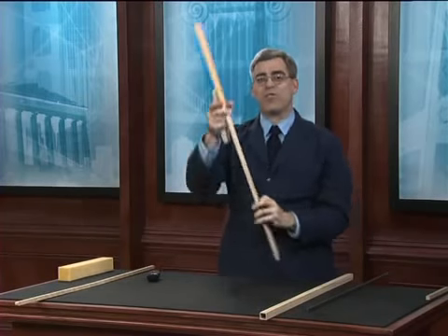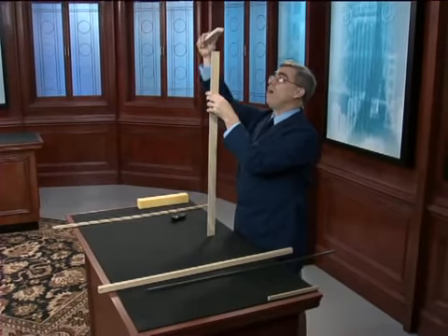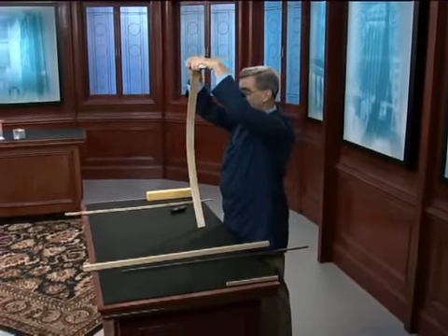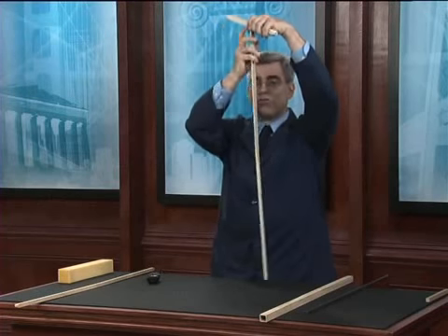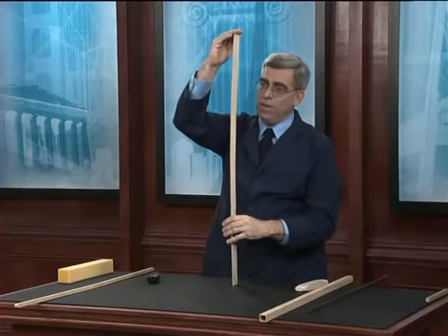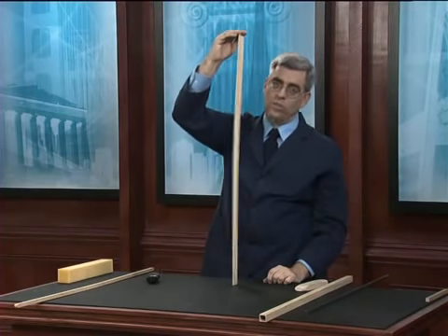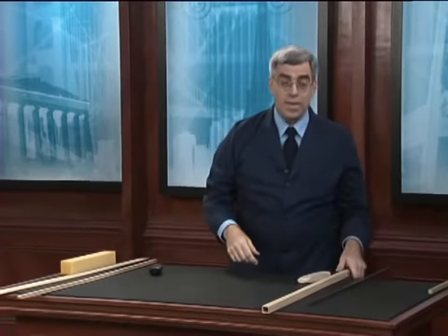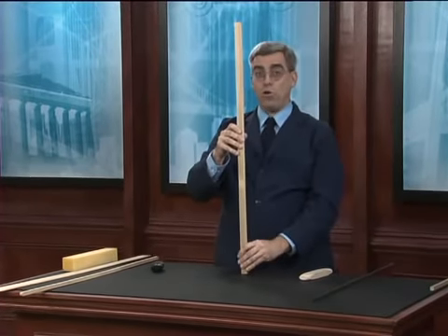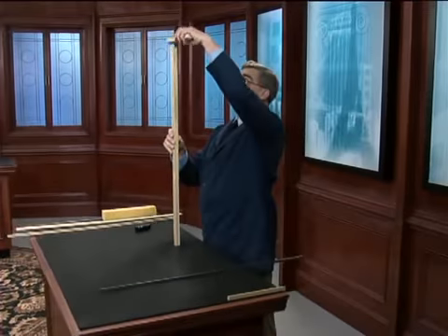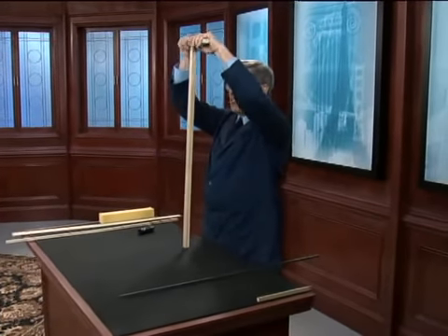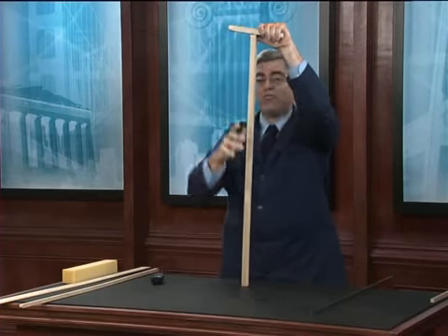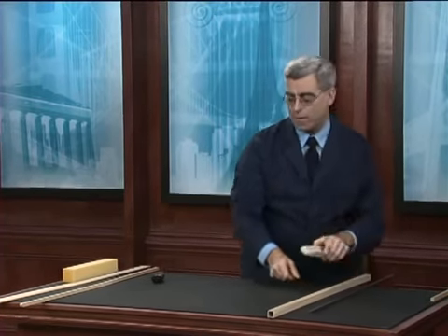And now let's try this flat plate. The Euler buckling equation tells us that this ought to buckle at a load of about 2 pounds, and indeed, it buckles at an extremely low level of load. Just a slight push causes it to kick out sideways. On the other hand, the calculated Euler buckling load for the hollow square section works out to be 200 pounds. And again, there's no way that I can actually buckle it by hand.